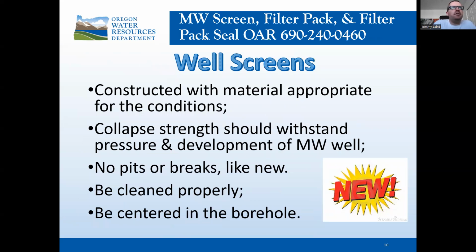Moving on to monitoring well screens, filter packs, and filter pack seal. You can find this in OAR 690-240-0460. Well screens need to be constructed with material appropriate for the conditions. They must have a collapse strength that should withstand the pressure and development of the monitoring well. There can be no pits or breaks. It has to be like new. They must be cleaned properly and must be centered in the borehole.